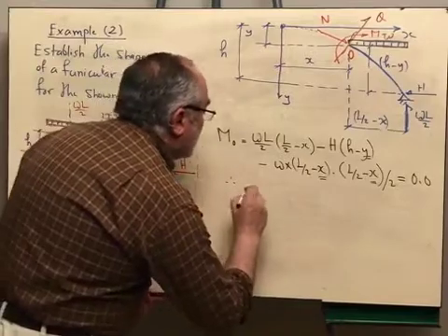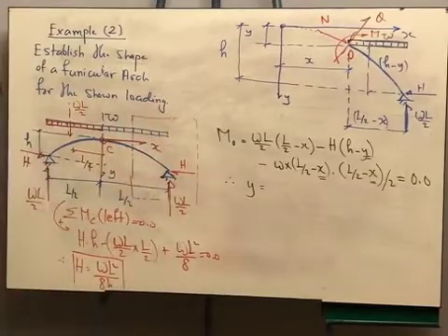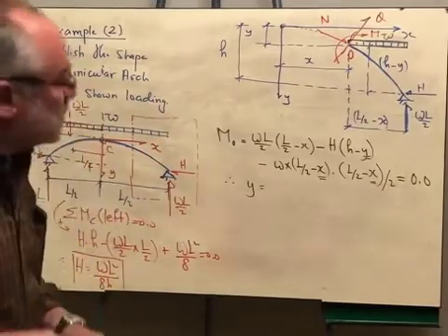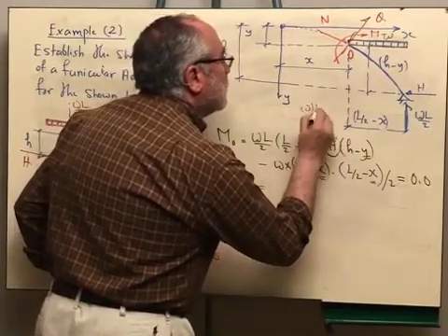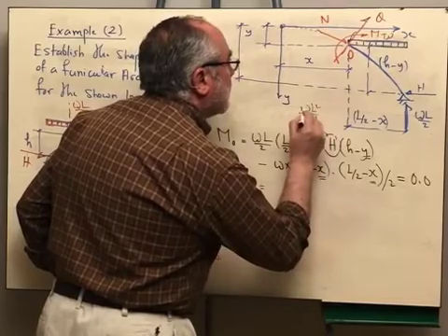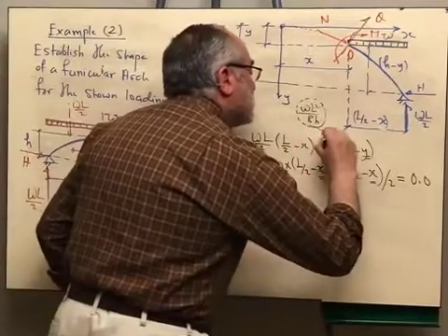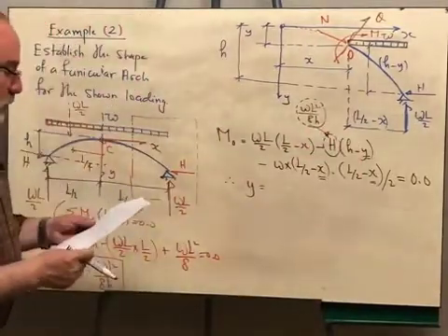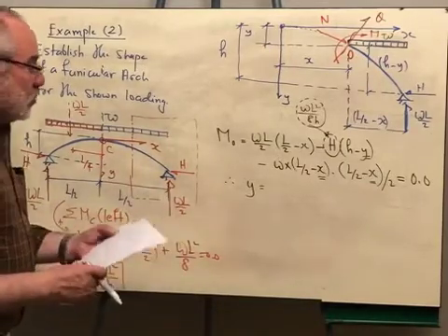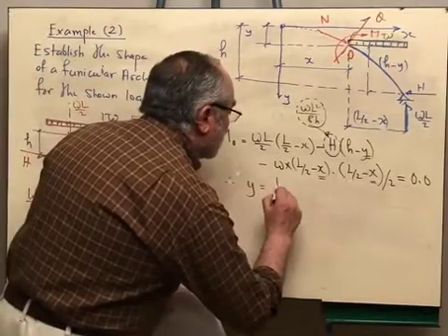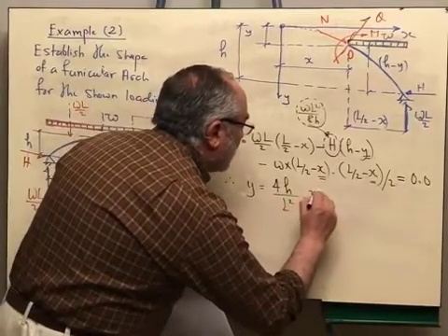So from there y is equal to, if you did this, of course you can cancel out the W's together and you can substitute here the magnitude of H is equal to WL square over 8h. Okay, this you can substitute by its value. So you can finally prove that the value of y is equal to 4h over L square multiplied by x square.